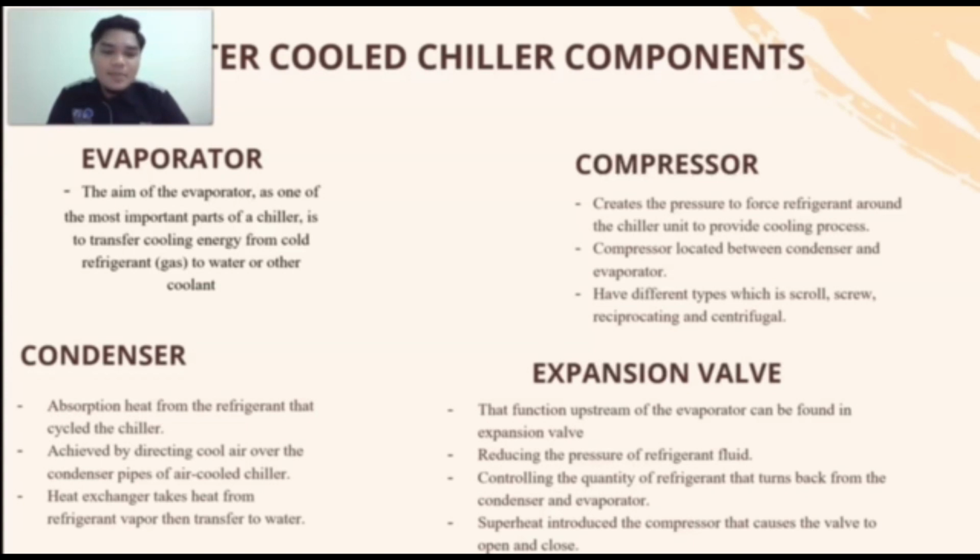So next is expansion valve. That function upstream of the evaporator can be found in expansion valve, reducing the pressure of refrigerant fluid, controlling the quantity of refrigerant that returns from the condenser to the evaporator. Superheat introduced to the compressor causes the valve to open and close.